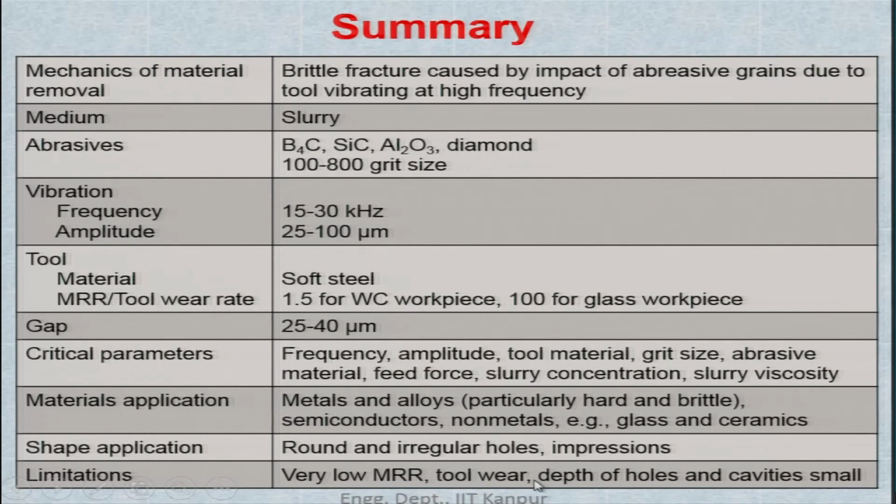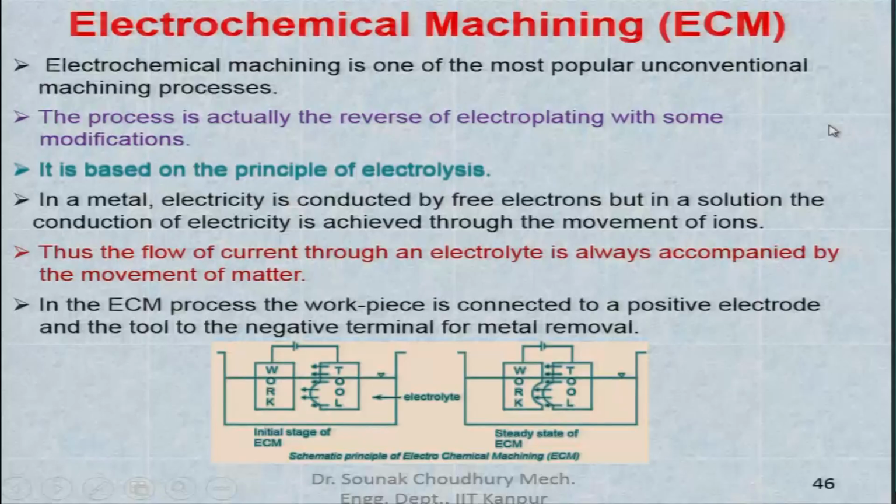Tool wear, because it is a high frequency process with abrasives, and therefore the tool wears out. The depth of holes and cavities is small, because if you go to a higher depth, the energy is not sufficient. That means you have to increase the amplitude and the frequency. All right.